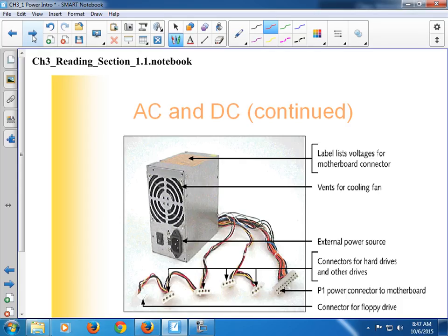So this has a little switch right there that says 115, and then you switch the switch. This now says 230. Okay, so this can be plugged in Europe right now. This computer will work, and now it's plugged into the United States, and this computer will work. Okay, it's just telling you what the input voltage is going to be. That's why it says 115, 230. That's a switching power supply that you can use in either location.